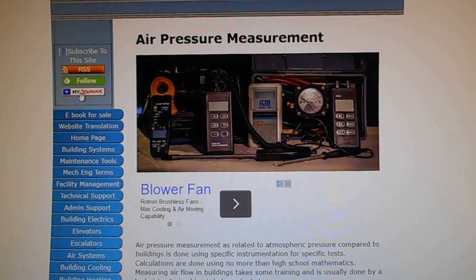Technicians, after setting the correct zone supply air volumes, then adjust individual supply air diffusers, balance dampers, to increase or decrease supply air to individual areas or offices. When the supply air volumes are correct, the technician must adjust individual return air grill balance dampers to increase or decrease return air flow from individual areas or offices.